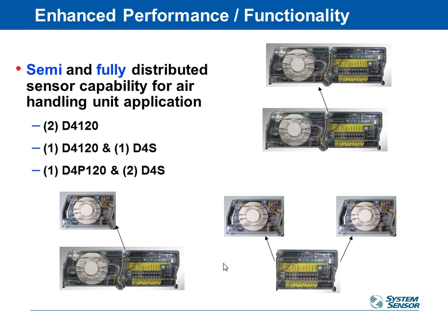So there's a lot of flexible things involved with this. The voltage is pretty flexible. The way you can install it vertically or horizontally is pretty flexible. Another thing that's pretty flexible about them is that these detectors can be installed, I don't know what's the best way to say it, piecemeal. So if I do have an application where I need to monitor both supply and return systems, which would mean that I have either 15,000 CFM or more, or I have 2,000 CFM or more in a jurisdiction that's regulated by both NFPA and IMC, then I'd have to have 2 detectors.